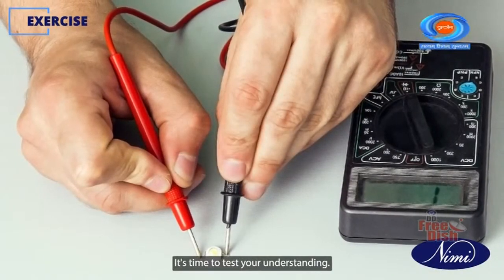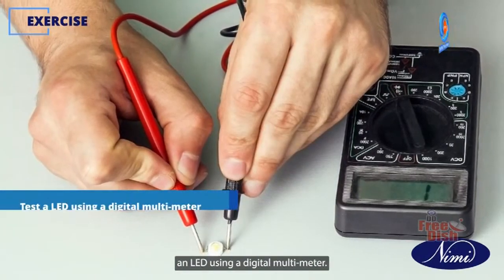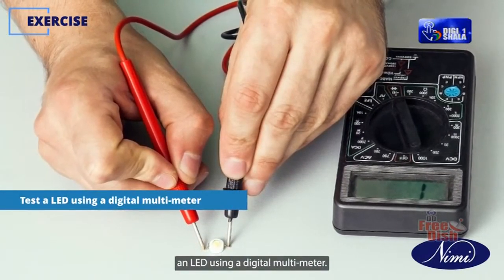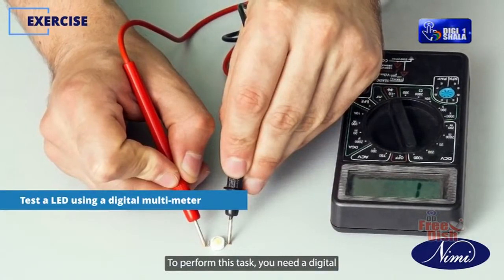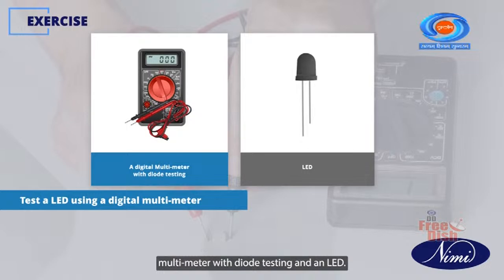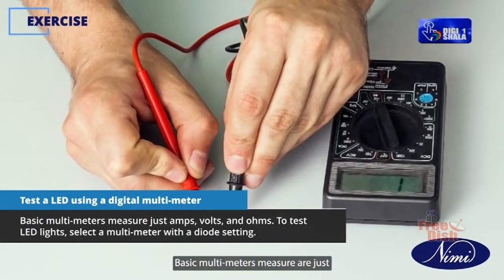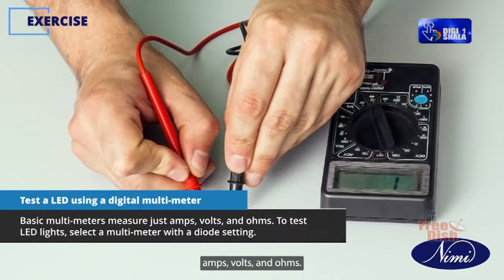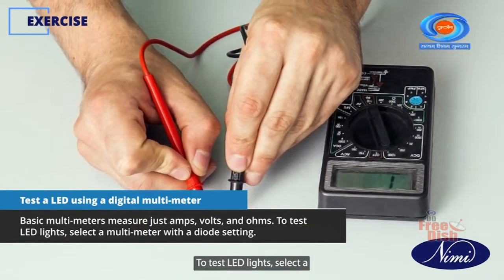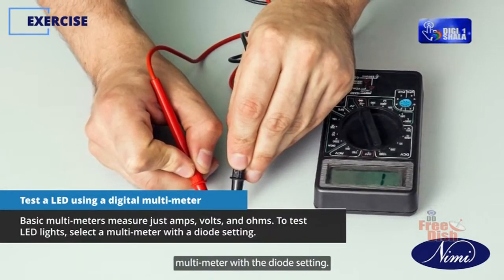It's time to test your understanding. Your first task is to test an LED using a digital multimeter. To perform this task, you need a digital multimeter with diode testing and an LED. Basic multimeters measure just amps, volts and ohms. To test LED lights, select a multimeter with the diode setting.